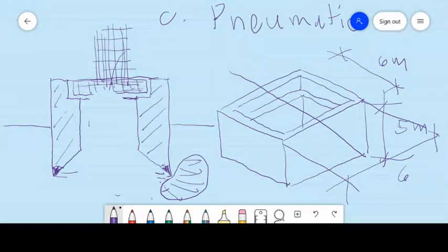Now the effect would be the caisson will tilt during sinking. And if this is not anticipated, the level of the caisson will be difficult to put back, or the plumbedness of the caisson is difficult to be reverted.